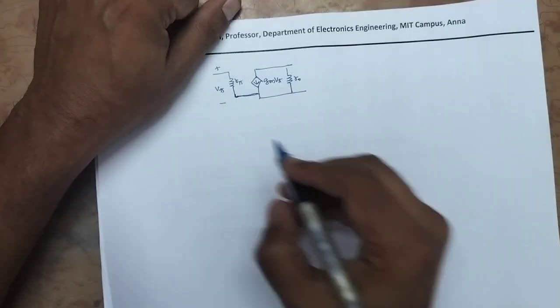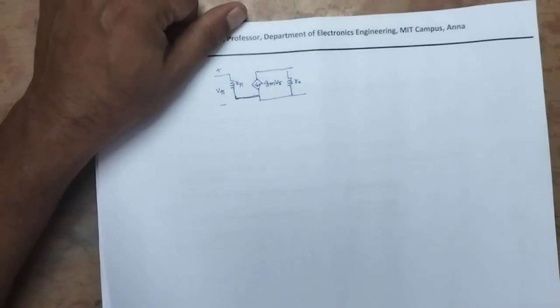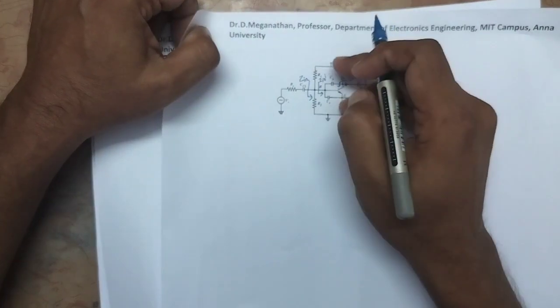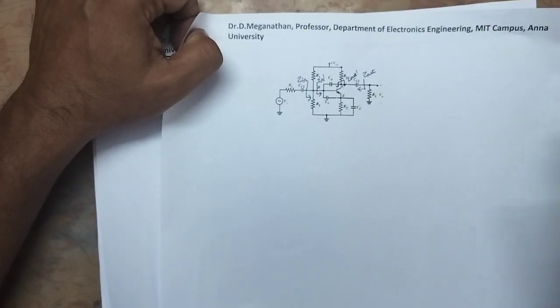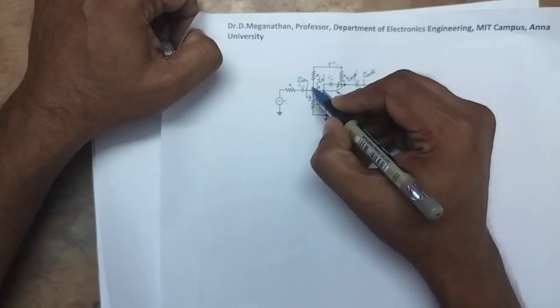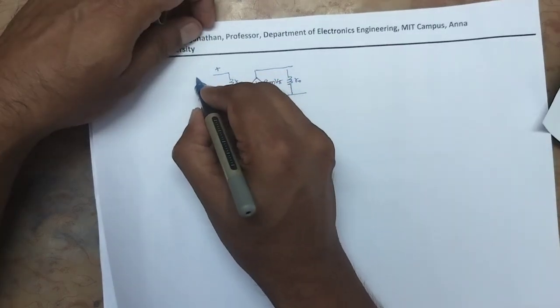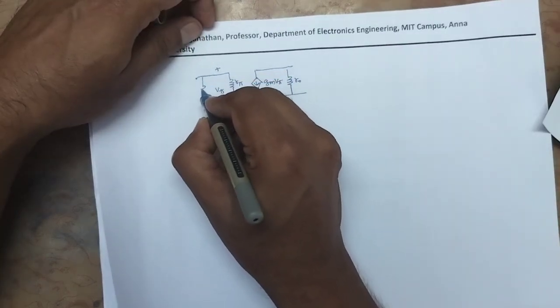So you have the R1 parallel to R2 resistance. We have to short this node, since VCC is an independent DC source. Here we have R1 parallel to R2, the biasing element.